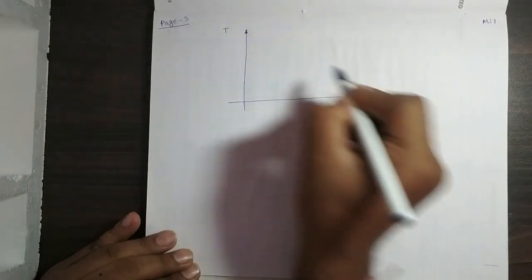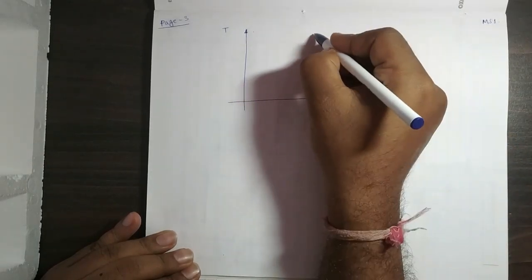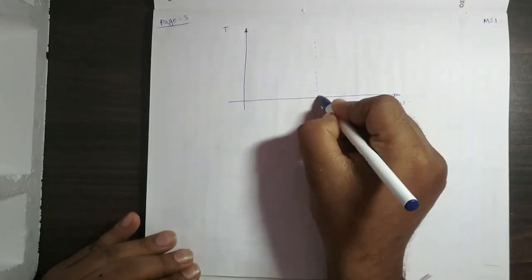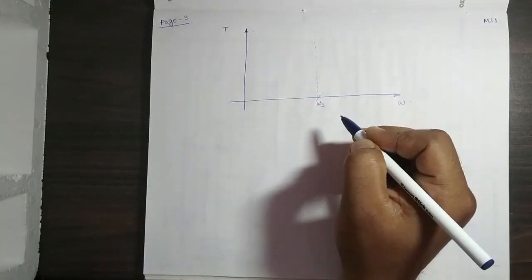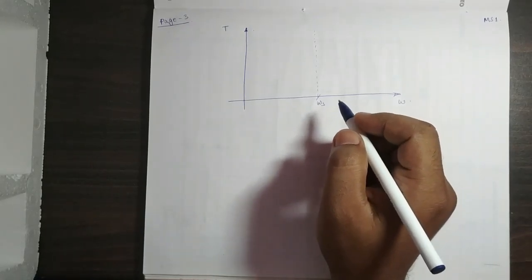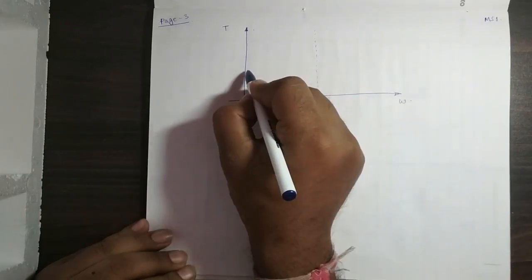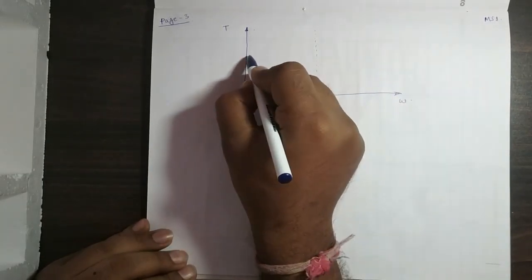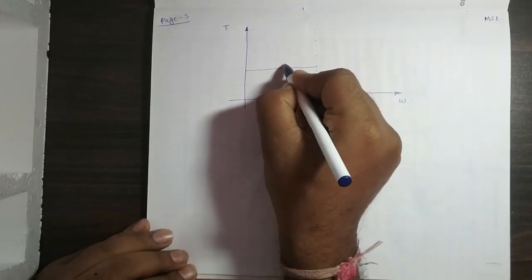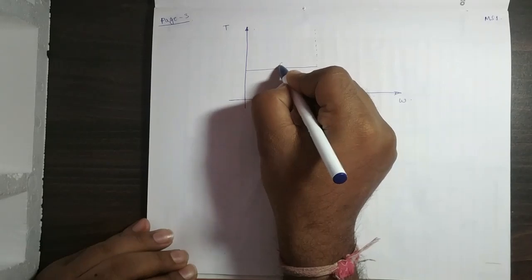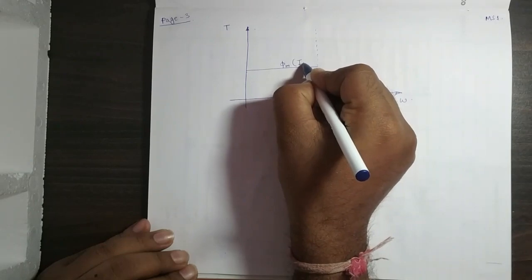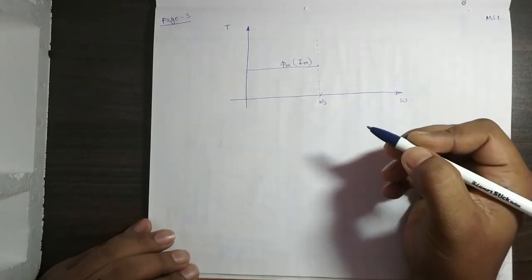So this is the torque, this is the speed. Here we are taking the base speed omega s. Till here the flux is constant, so this is the flux line. This is effectively equal to psi m, which is a function of Im, or magnetizing current, right?